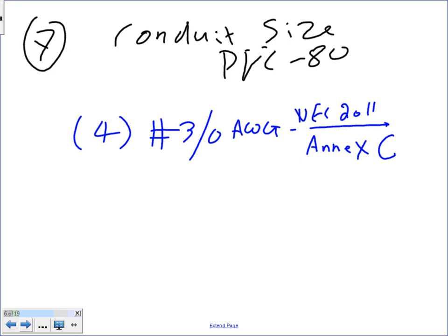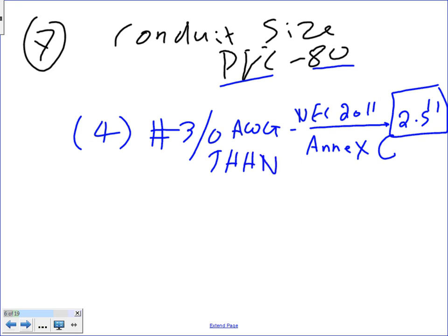And by the way, what type of conduit do I want? Up to this point, have I told you guys what type of conduit I want? PVC Schedule 80, did I write it down? Yes, right here, PVC Schedule 80. And what do I need? 2.5 inches. The conductors' insulation we should write too: THHN. It defeats the purpose if you're using PVC, most likely it will be THHW, but we are pulling it in a dry location, THHN.